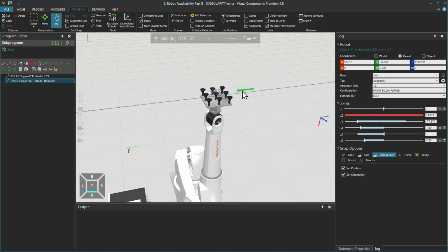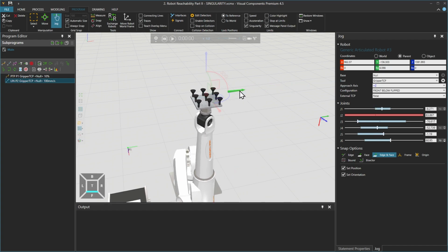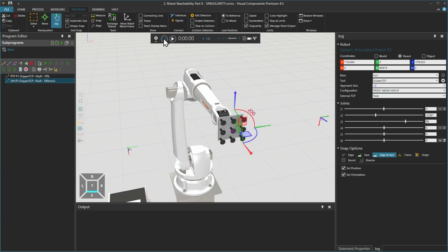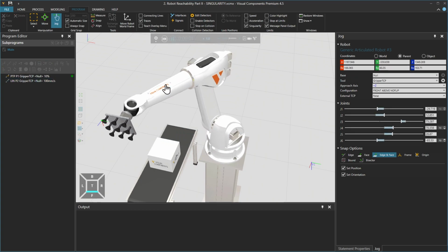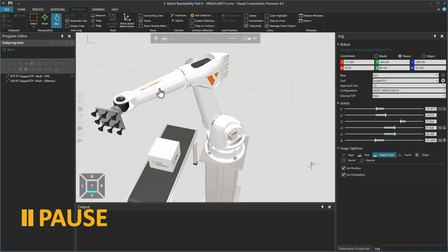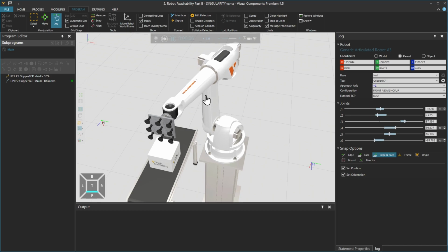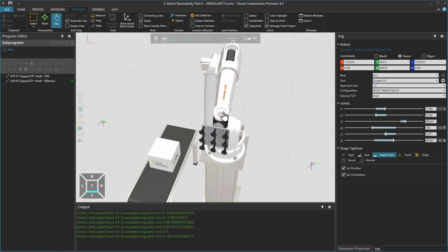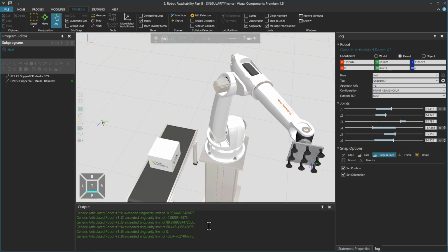If we're given the same positions of joints J4, J5 and J6, wrist singularity may also occur. So now we have the jog panel visible, we will reset and run the simulation to see if singularity occurs. The robot will first perform the PTP motion where singularity will not occur, and while performing the linear motion, when we reach the point where joint J5 is at 0, we will see the joints flip, and an exceeded singularity limit message will appear in the output panel below.